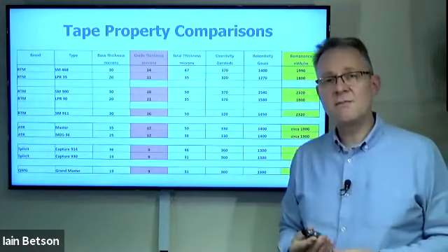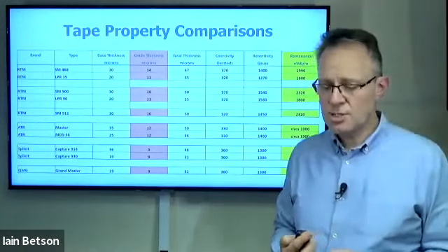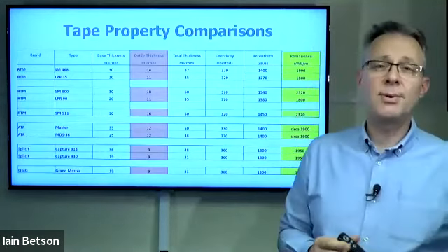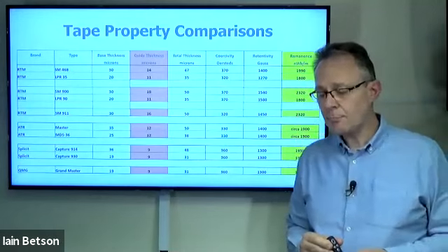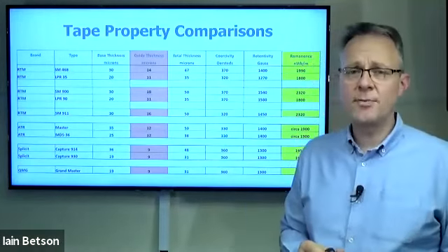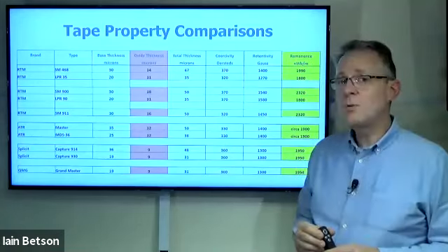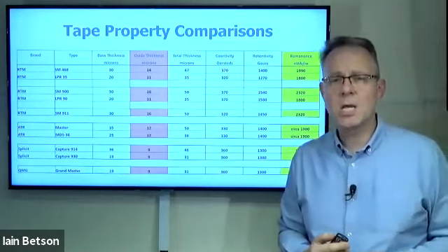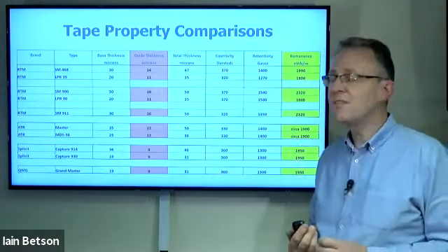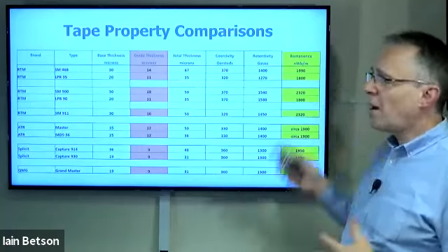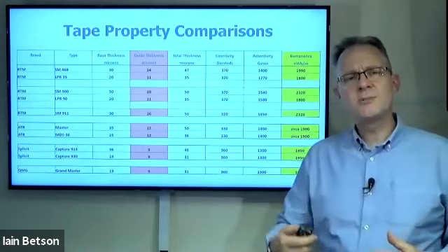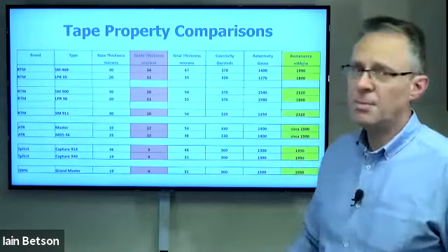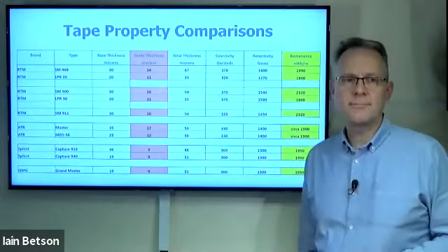The flip side is, if you're in the recording industry and you're using it professionally, I think SM468 is still a good tape. I said the BBC selected it as their standard tape from Agfa, and in my days we were using 2-inch 468 to record on. This is late 1980s, early 1990s. Perfectly good results. But again, if you wanted to step up and feel a bit more confidence that you're pushing as much level onto the tape and you've got a lot of headroom, you could jump up to your SM900 tape and use that.